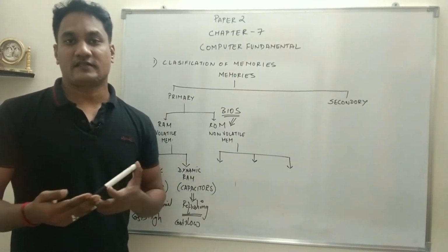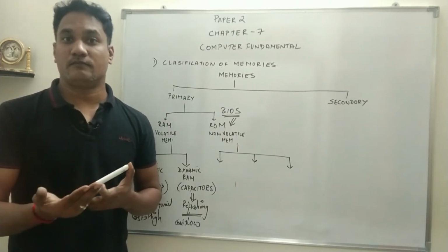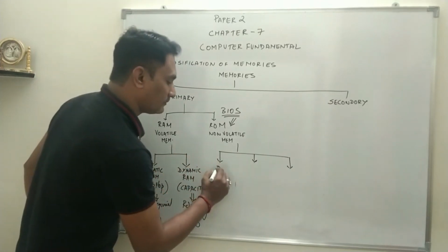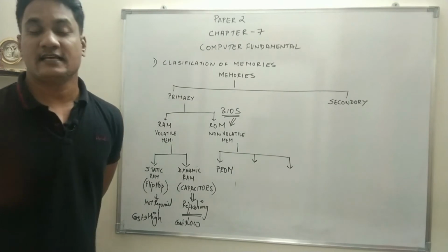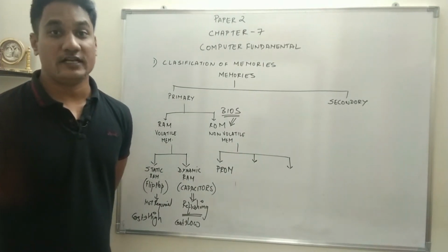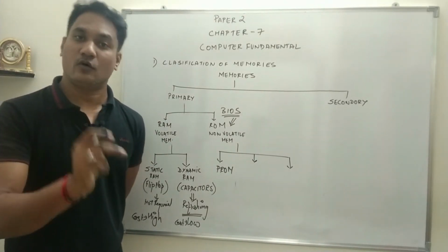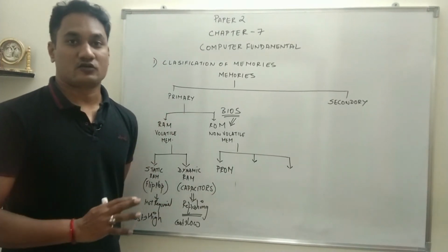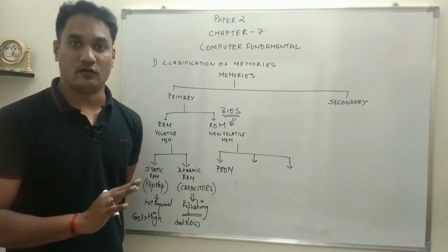But then after some decades, there was a necessity that as a user I should program my computer. So there was one more modification which has been done, called PROM. PROM stands for programmable read-only memory. That means as a user I can program it, but once it is programmed, it will become ROM. That means you cannot store the information once again in the memory. It has to be read only.